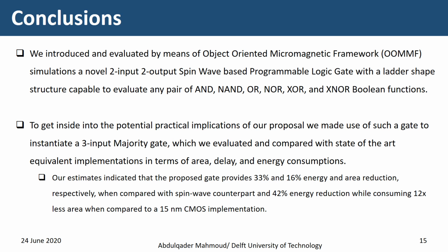Our estimates indicated that the proposed gate provides 33% and 16% energy and area reductions, respectively, when compared with the spin wave counterpart, whereas 42% energy reduction while consuming 12 times less area when compared to a 15 nanometer CMOS implementation.